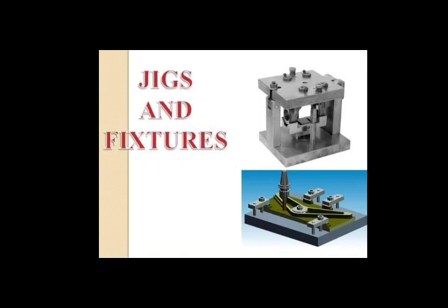You will come to know all these concepts in the subject of metrology, but you should know the basics of this. So, what is the difference between jigs and fixtures? The function of jigs and fixtures is the same, that is to hold the workpiece accurately and precisely onto the machine table and to achieve a higher production rate in the manufacturing of identical parts. The basic difference is that a jig provides tool guiding and setting arrangements, whereas no such means are provided in the fixture.